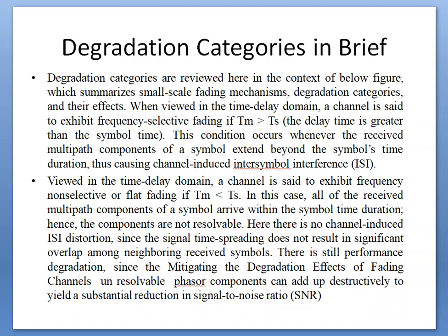Here, there is no channel induced ISI distortion since signal time spreading does not result in significant overlap among the neighboring received signals. There is still performance degradation, since unresolvable phasor components can add up destructively to yield a substantial reduction in the signal to noise ratio.